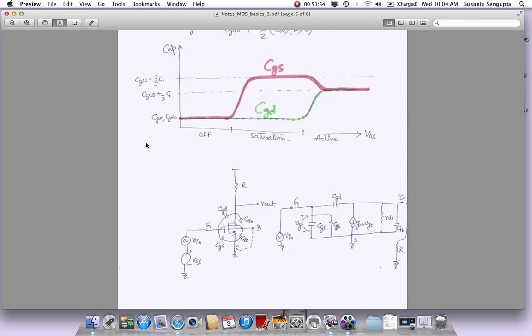So a low pass filter remains flat. Let's say it's a gain, it will remain flat like this, and then it will roll off over frequency, where this x-axis will be frequency. All of them have a low pass type filter response. And that roll off happens because of these parasitic capacitances, which we cannot avoid. Now when you have these parasitic capacitances and you can't avoid them in a technology, how could you do a more high frequency design, given that you have to live with these capacitances?